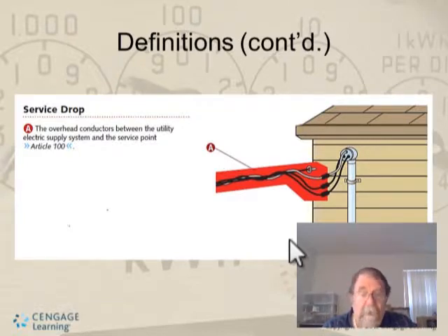Special permission and authority having jurisdiction. Special permission is the written consent of the authority having jurisdiction, which is the AHJ. This is in Article 100. And the AHJ is the organization, office, or individual responsible for enforcing the requirements of a code or standard, or for approving equipment, materials, an installation, or a procedure. And they can grant exceptions by written permission for those issues you may be having.